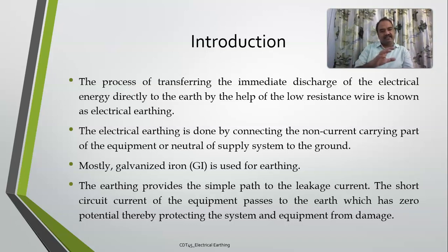It is because electrical energy is moving on the surface of these bodies. So you should ensure that whatever electrical discharge is there on the surface of the body must not go to us. It must not pass through us. It must directly go to the ground, because the ground is a very good absorber of everything, right? It is electrically considered as neutral, so any charge it can directly take. So we should ensure that all these equipment are provided a path to the ground, such that even if we touch them, we don't get any electrical shock.